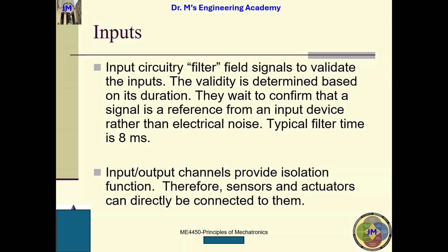So input and output channels provide an isolation function. This is what I told you guys, okay? Therefore, sensors and actuators are directly connected to them. Within the input channel and output channel, we have opto couplers to protect our PLC system from being destroyed by the high voltage from the outside system.